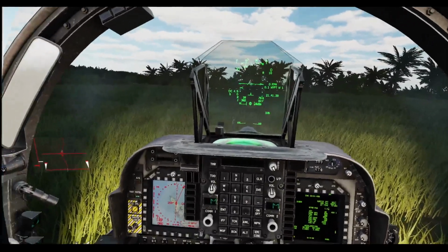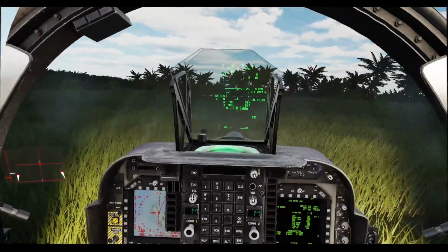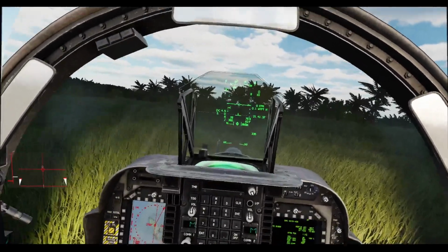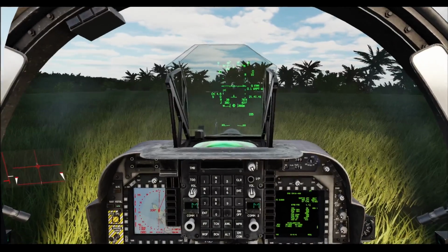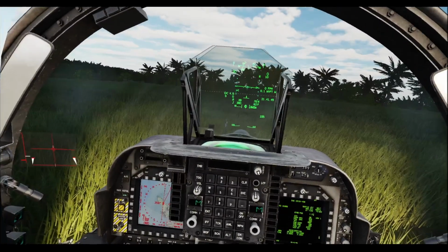Okay, so obviously in this scenario, I didn't touch the nozzles as we got in close. However, in a real world scenario, you might choose to bring them to the hover stop or even the braking stop to help you slow down and to get a little bit more jet-borne lift as you come in the terminal stage of the approach. That can really help you reduce the amount of surface area that you're using up.